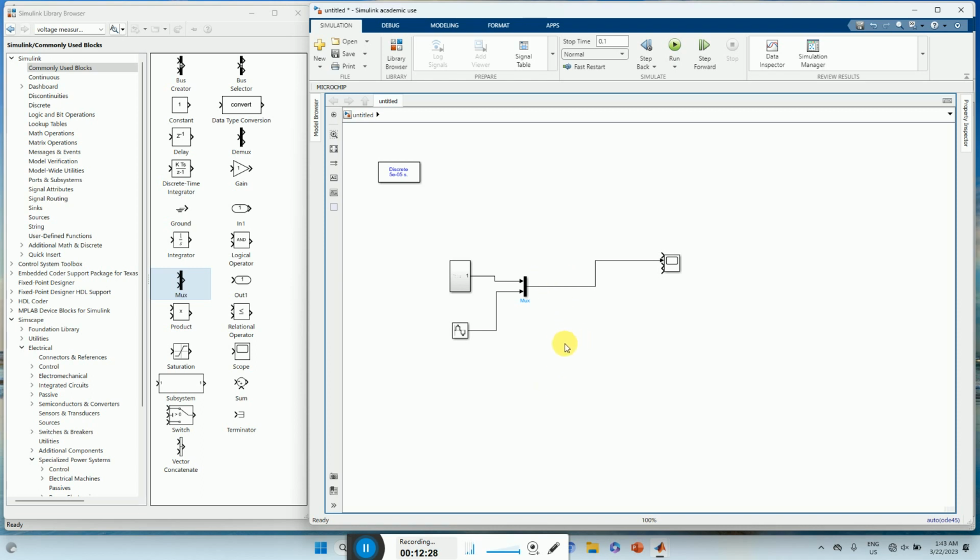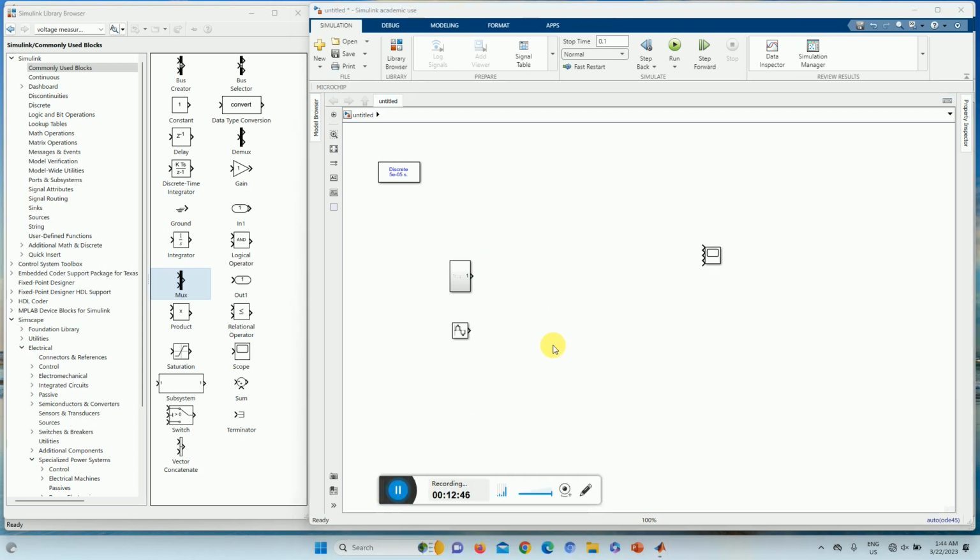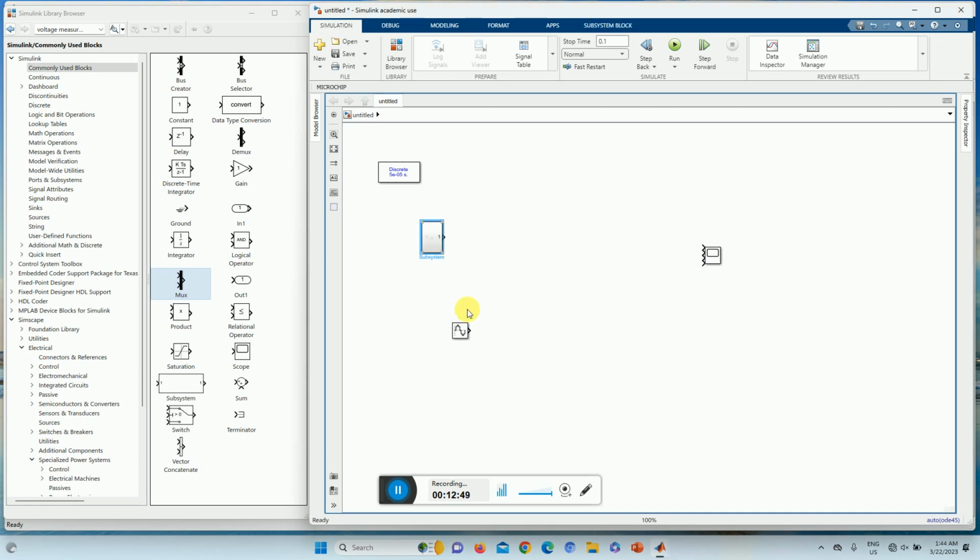Ultimately our objective is to generate a triangular wave and a sine wave, and then to have an SPWM inverter, right? So we have tested. This is no more required. Ultimately, we have a sine and triangular wave. We keep this aside. Now we will make an inverter, a 3-phase inverter.